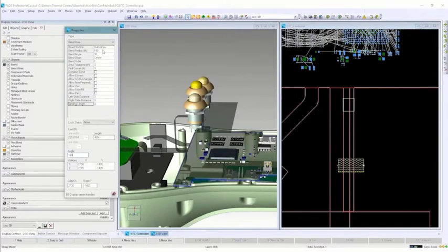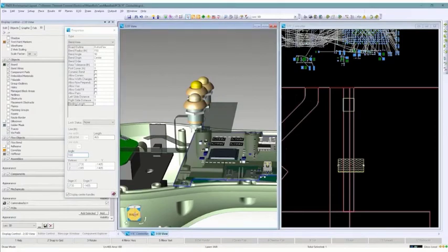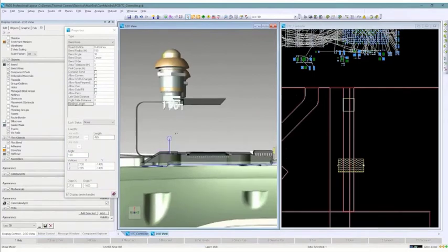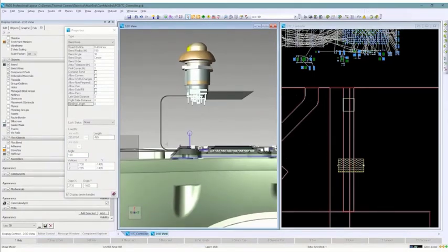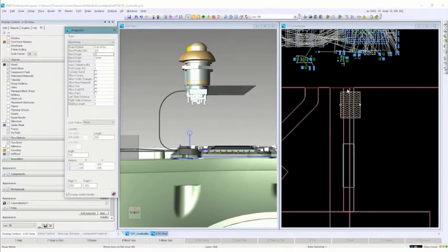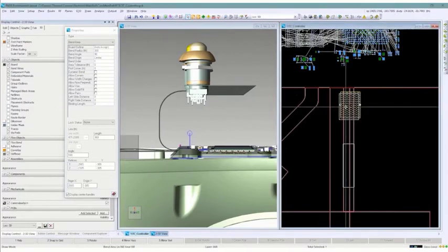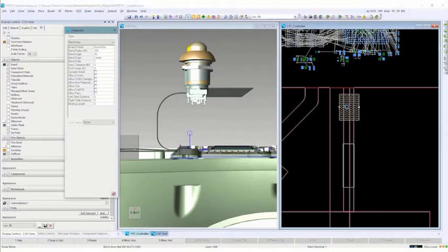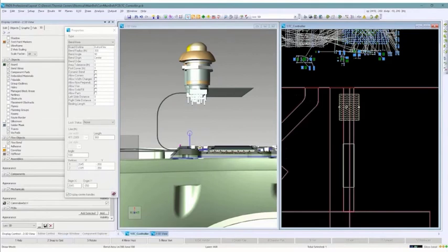And then again, I can adjust the proper parameters here. So we can leave that at 90. You can see it automatically bent it at 90 degrees for us because that was the default. But now I need to start adjusting these angles or these radiuses here. We can control how far the bend is from the rigid area of the board. That is another constraint actually that you must follow. You have to have a certain distance from the rigid edge of the board to where the bend starts in order for it to not break or have assembly issues.